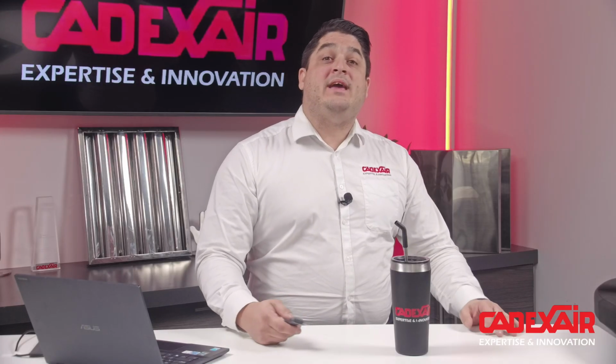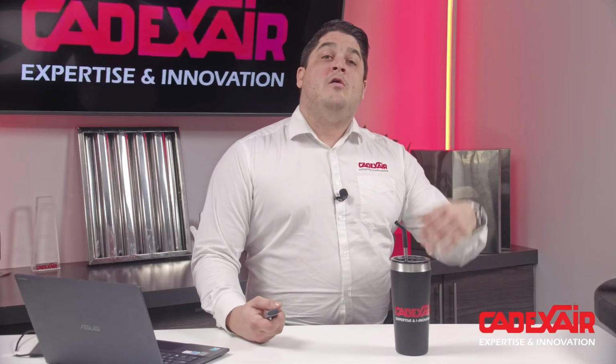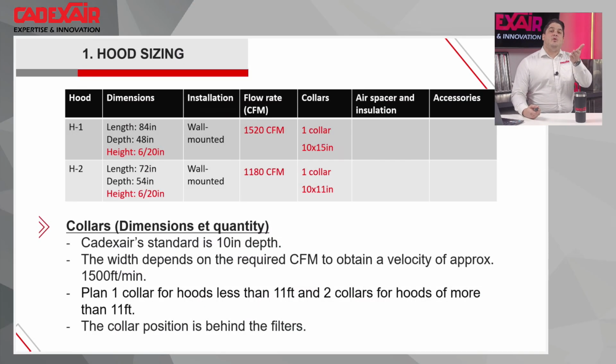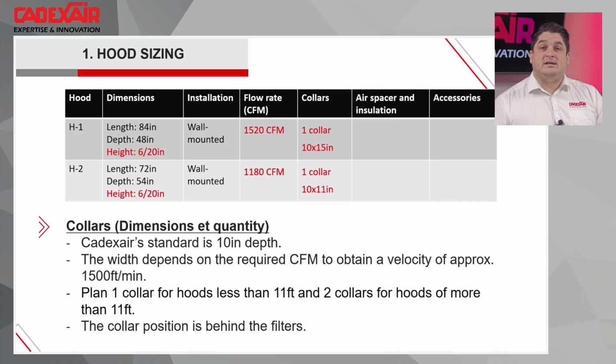So we calculated the airflow for the kitchen exhaust hood: 1,520 CFM for H1, 1,180 CFM for H2. Now we have to put our duct collar on the kitchen exhaust hood. Normally at Cadexair, your duct collar is 10 inches deep. I will explain a little bit later why. After that, we try to have something around 1,500 feet per minute inside of our ductwork. This is how we control the width of the ductwork.